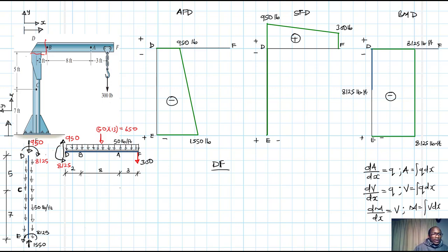So from there onwards, what do we have? We have shear, which is equal to this diagram. See this diagram? We have shear, which is positive and decreasing, right? It's decreasing in slope, and therefore we expect the slope of our moment also to be positive and decreasing, right? And what is magnitude? Magnitude is just the area under the shear diagram, which in our case is just a trapezoid.